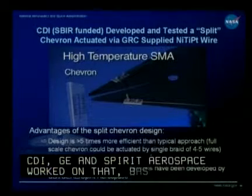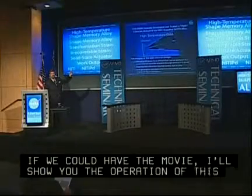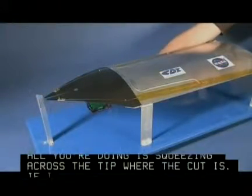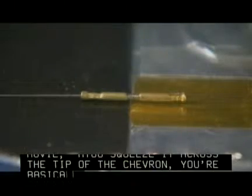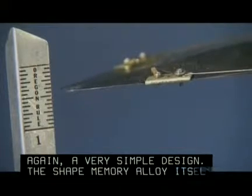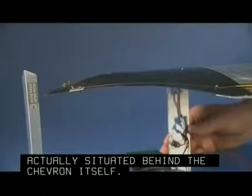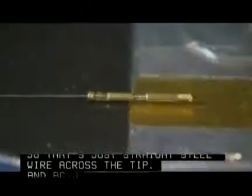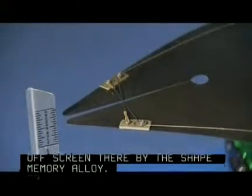But if we could have the movie, I'll show you the operation of this chevron. Basically, all you're doing is squeezing across the tip where the cut is. So as you squeeze across the tip of the chevron, you're basically forcing it down and causing it to deflect. So it's, again, a very simple design. The shape memory alloy itself is actually situated behind the chevron. That's just straight steel wire across the tip, and the actuation force is applied by the wire that starts basically off screen there by the shape memory alloy. Basically, this is the connection between the steel cable and the shape memory alloy itself.